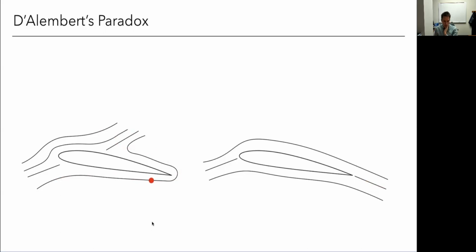And this is not possible with any viscosity because I have such a huge velocity gradient. The shear stresses would be enormous. The boundary layer flow, or the flow near the body, is in no way going to be able to navigate such a huge velocity gradient without separating. So I need some way to impose this. Potential flow won't do this automatically. So I need to impose this somehow.